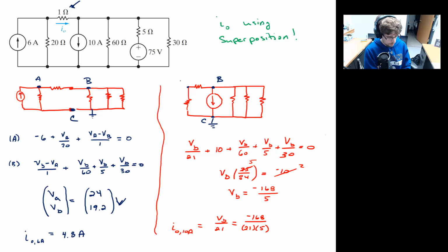Yeah, I'm not seeing it. Might be a common 7 in there somewhere. Yep. Must be a common 7 and a common 7 and a common 3. This ends up being 8/5. So 1.6 amps. Notice the negative sign, which I've tried to drop twice. And the fact that we have a negative sign means it's going into node B, not away. And so this current is going from left to right, as was this current, left to right.